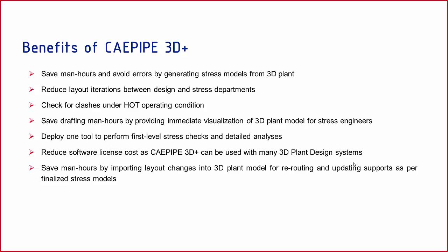Then as the stress analysis is done, of course you save drafting maneuvers, because you're going directly from 3D plan design into stress model. The drafting maneuvers are all eliminated, and then you have one stress tool, which covers both the first level stress check by the designers as well as detailed analysis by the stress engineers, and that in turn reduces the software cost.